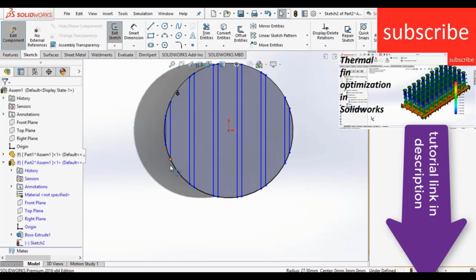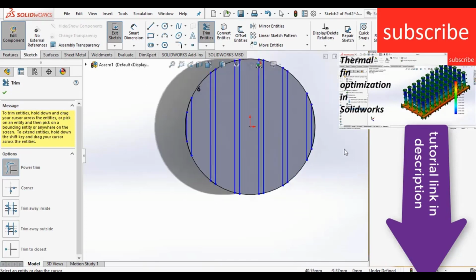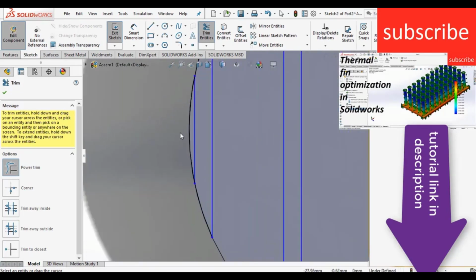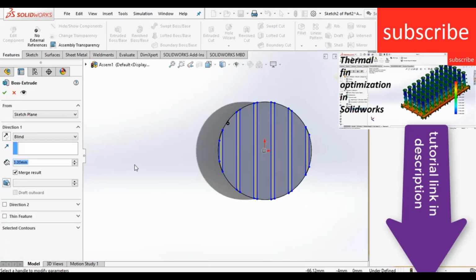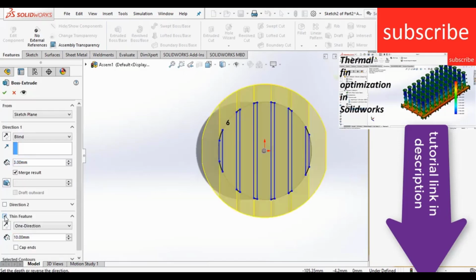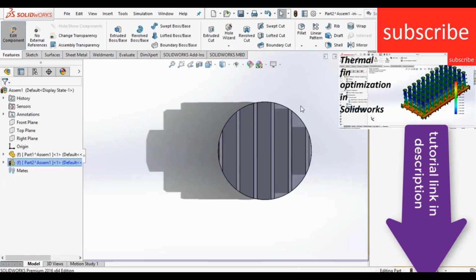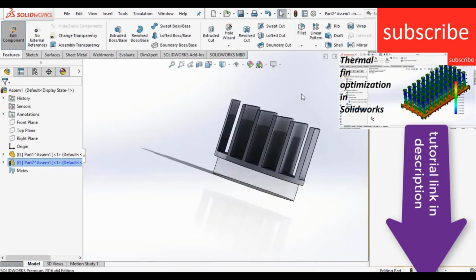Press Ctrl plus Z, click on trim entities, and trim this, and the last line here is this. Now go to extrusion, click on extrude boss base, make it extrusion up to 30 mm. So this is basically our fin.